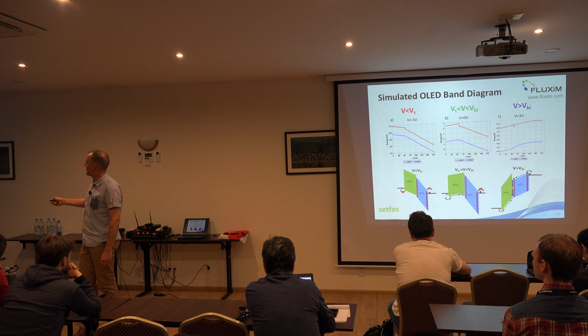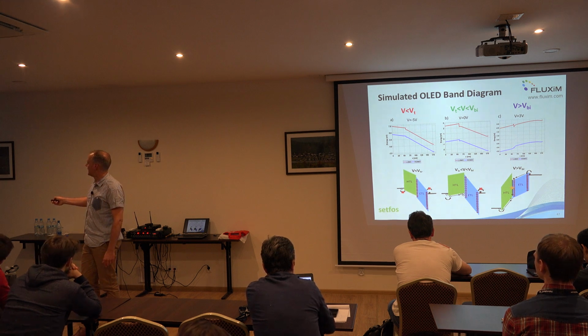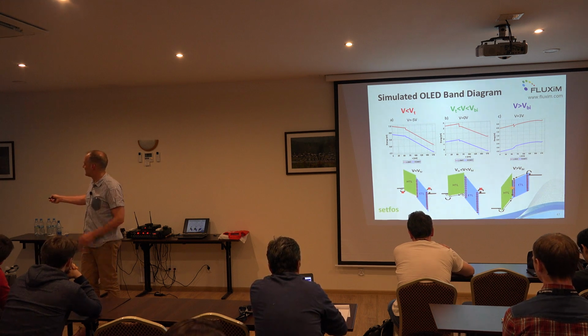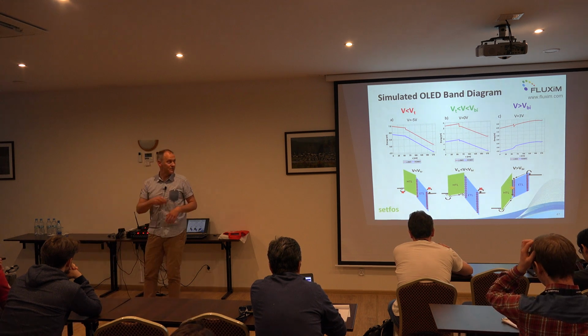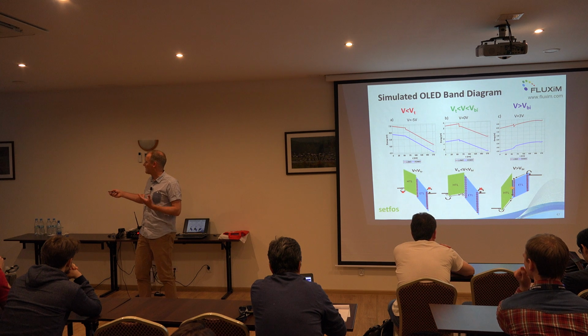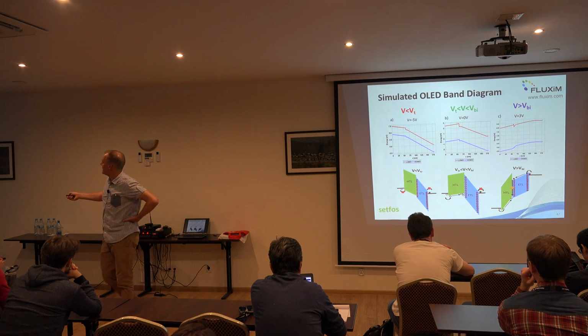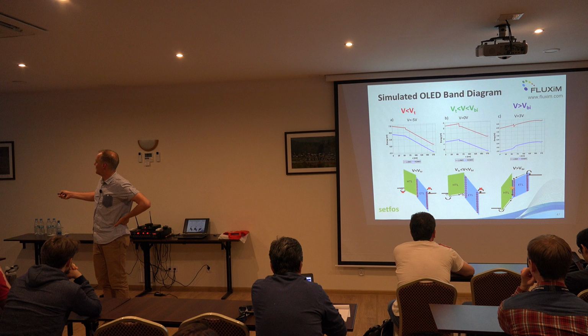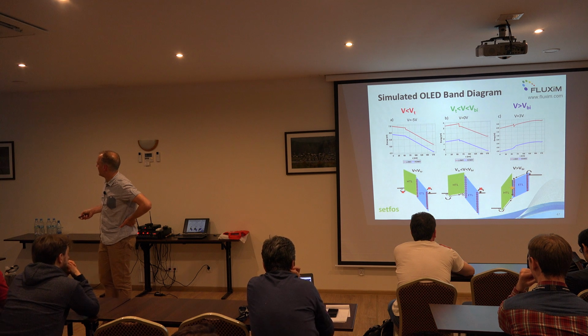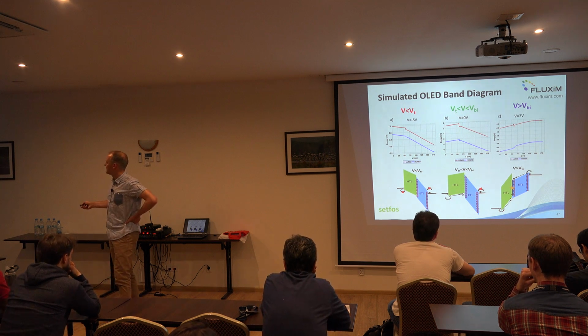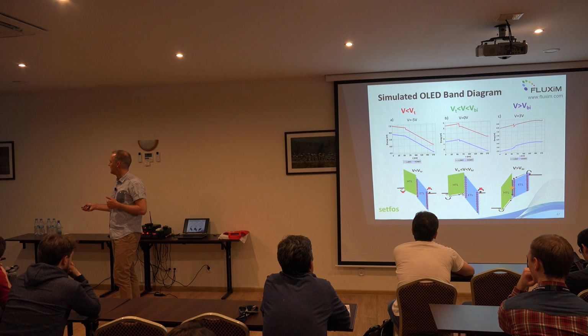If you go much lower in voltage, then the band diagram, this is simulated. The upper diagrams are simulated, the lower one is just a sketch, but they coincide nicely. You see that if you go strongly negative in voltage, then you just pull out all residual holes or electrons, and only in the intermediate range you have one carrier type, namely the holes.